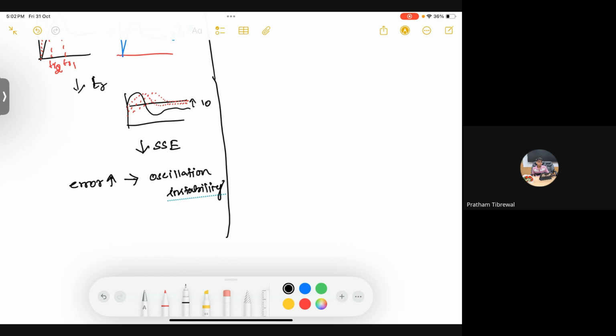So we can use this proportional controller if your system is already stable, then it is safe to use a proportional controller. The proportional control won't make the system go from stable to unstable because it is not introducing any zeros or poles, or disturbing the location of the poles of the system, because we are not adding any S to the system, right? So it won't change the stability nature of the system, and you can use this whenever the steady state error is small and acceptable, or it's very simple. Otherwise, you have to use this proportional controller in combination with other controllers.